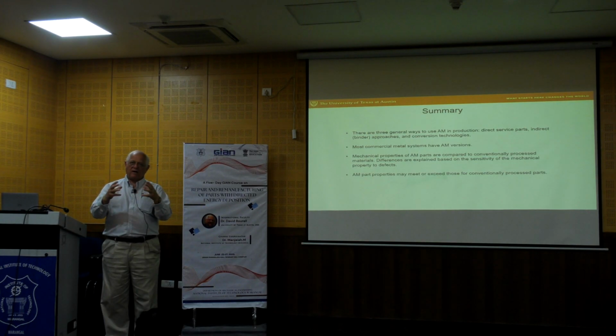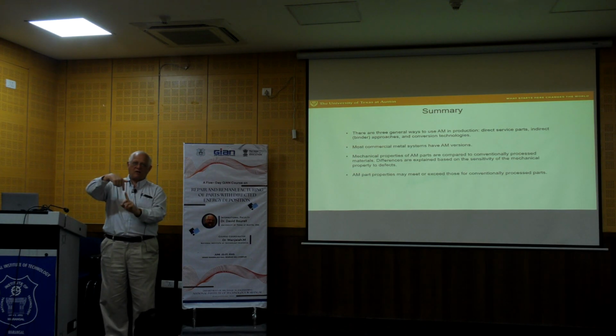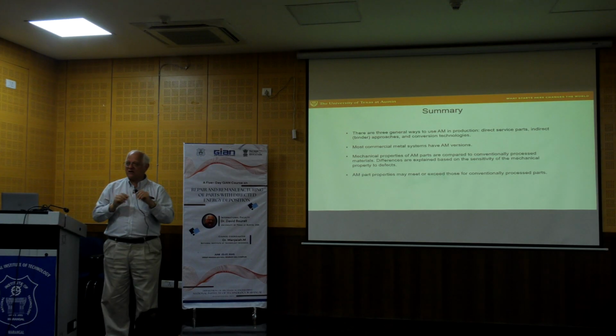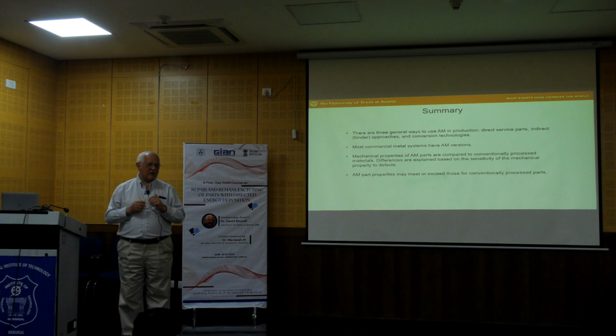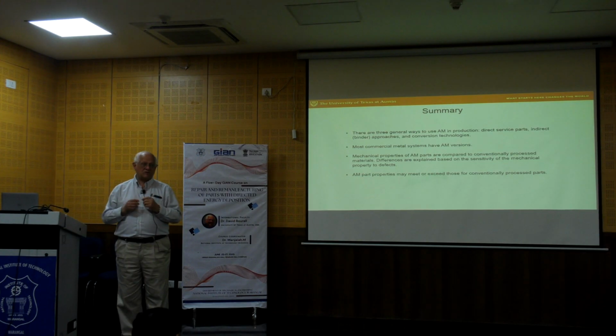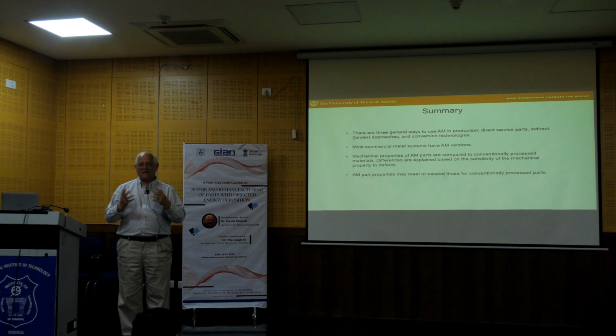So, for example, for an additive manufactured part, they'd do a tension test in the plane and then do a tension test in the build direction. They get largely different values, and they say, well, the material's inherently anisotropic. My response is no, it's not inherently anisotropic. What you have is a poor build. Because if the build is done with high quality, the anisotropy largely disappears.